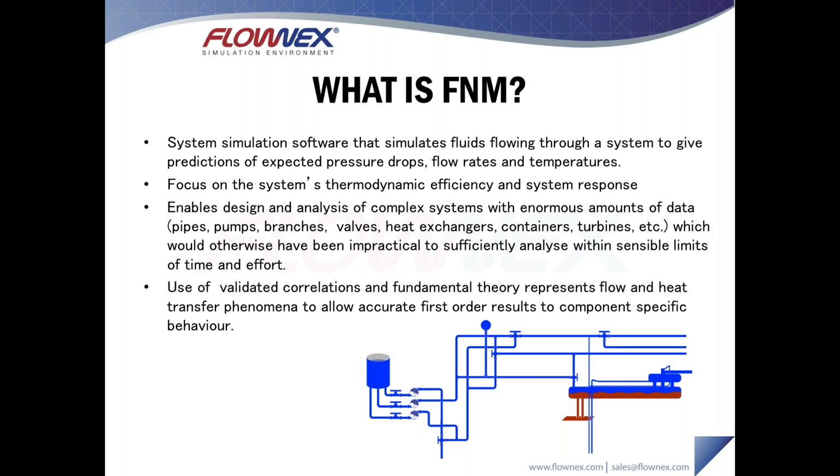Anyways, so flow network modeling itself. Basically this is a system model where pressure drops, pressure rises, and heat transfer are taken into account by small building blocks. See them as components in the system, such as a pump, for example. The actual physics inside of that component are then modeled with empirical correlations. So it has governing equations for our conservation of mass, energy, and momentum, coupled to empirical correlations to calculate pressure rises or pressure drops inside of the system.